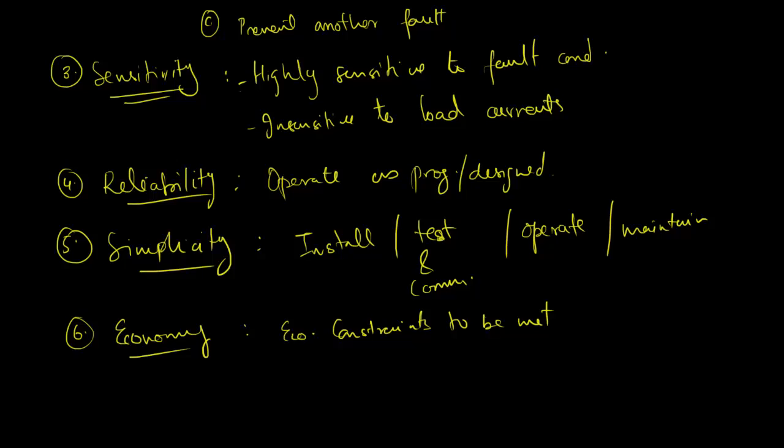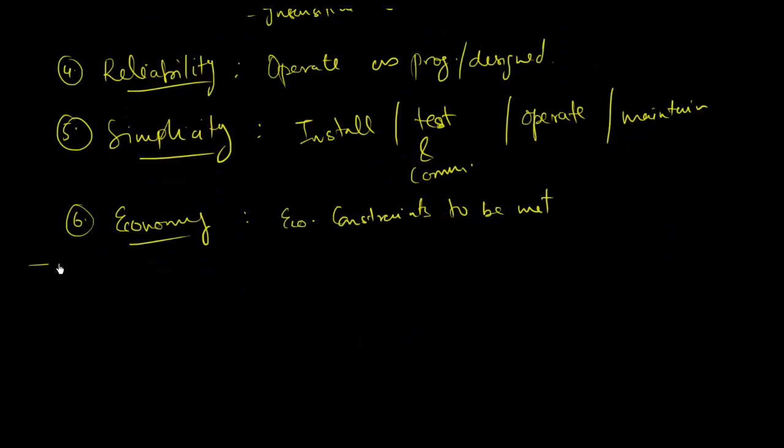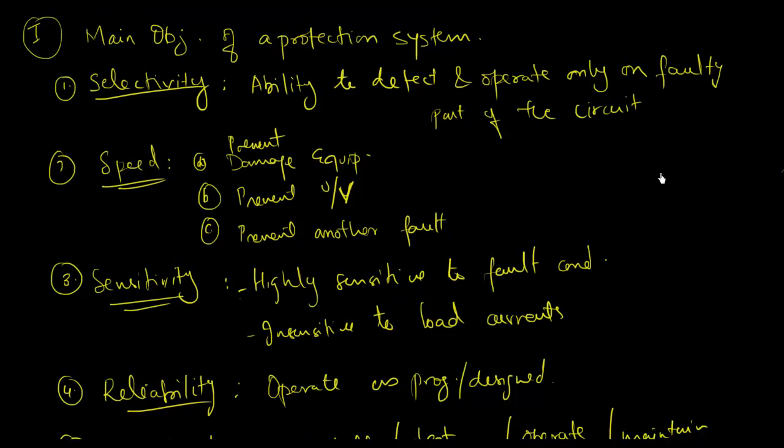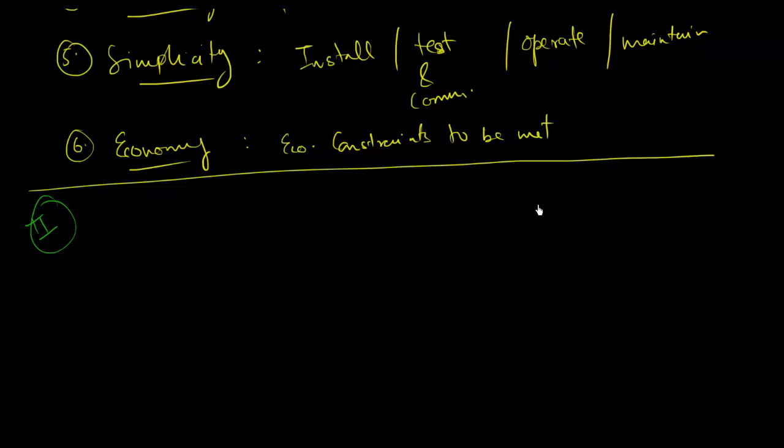So we've gone through these, and one other thing that I wanted to bring your attention to, which we spoke about in the question itself. As I mentioned, coordination amongst all the objectives that we have, coordination fits in selectivity. This is where coordination fits in. And then when you're designing or coordinating a system, you have your primary zone of protection versus your secondary or backup zone of protection.